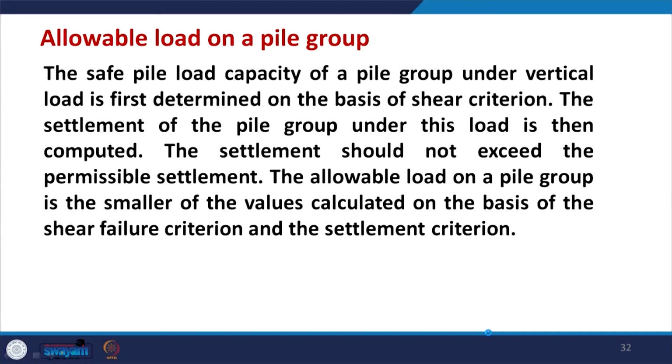So, this was regarding the settlement of a pile group, and finally, we come to the allowable load on a pile group. When we talk about allowable load, naturally, as for shallow foundations, the same is true for pile foundations. It will be governed by the two criteria which we have discussed. The load under vertical load is first determined on the basis of the shear failure criteria, then the settlement of the pile group under this load is computed, and the settlement should not exceed the permissible settlement.